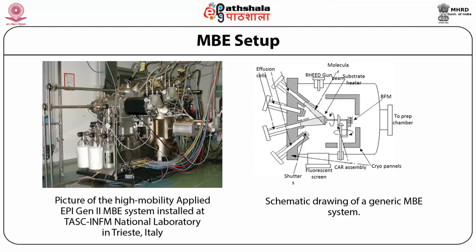It has slow growth rates which provide for great control over the epitaxial layer thickness, excellent thickness uniformity, minimal foreign contamination as a result of UHV conditions, real-time in situ characterization during growth, and high quality multi-wafer growth for high volume production.